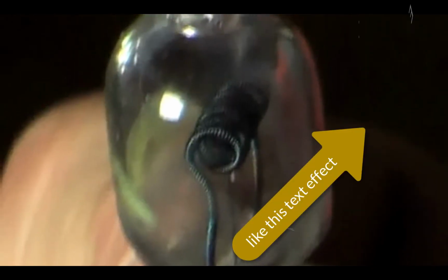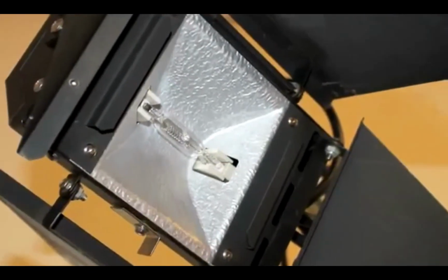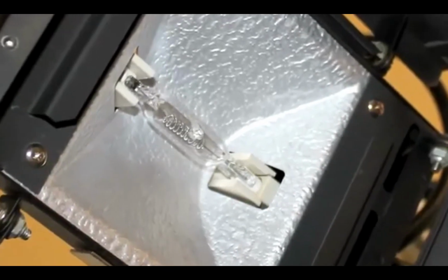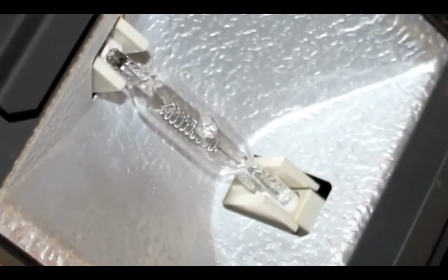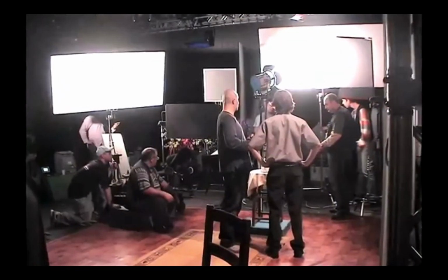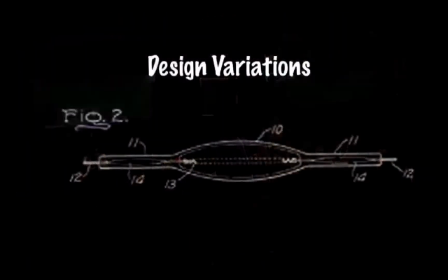So when you install a quartz lamp that has no outer bulb, no outer envelope, always hold it with a piece of tissue, or like I'm doing, hold it by the base so you don't touch the quartz. If you do touch the quartz, use rubbing alcohol and tissue paper to clean it off before you put it in service, and you won't have a problem.